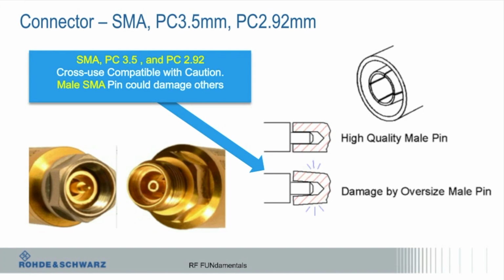How to detect that? Well, the main thing, you can't really see this once it's connected because obviously it's threaded. But if you look at this here, the center pin, you see there's like 4 little slots. If you looked at it carefully or under a microscope, I'm blind so I can't see squat. But that thing should be pretty much tight right together. Those spaces should be minimal on all 4 of those spaces. And if you see sometimes one of these might be bent back a little bit or the spacing is different, that's when you go, yeah, maybe this connector's damaged.